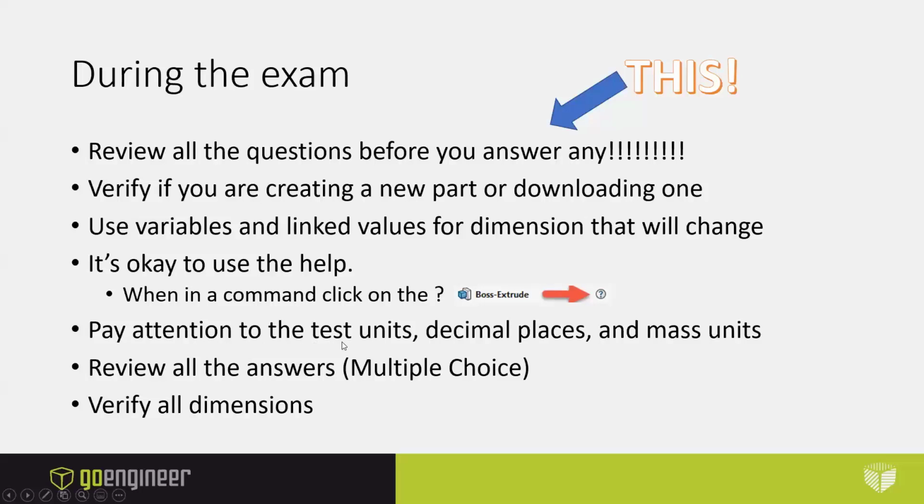Do pay attention to the test units, the decimal places, and the mass units. Not saying that they're trying to trip you up, but they may say build the part in inches using the inch, pound, seconds, and then when it asks you for the mass, it might ask you for the mass in grams. So again, pay attention to what they're saying.